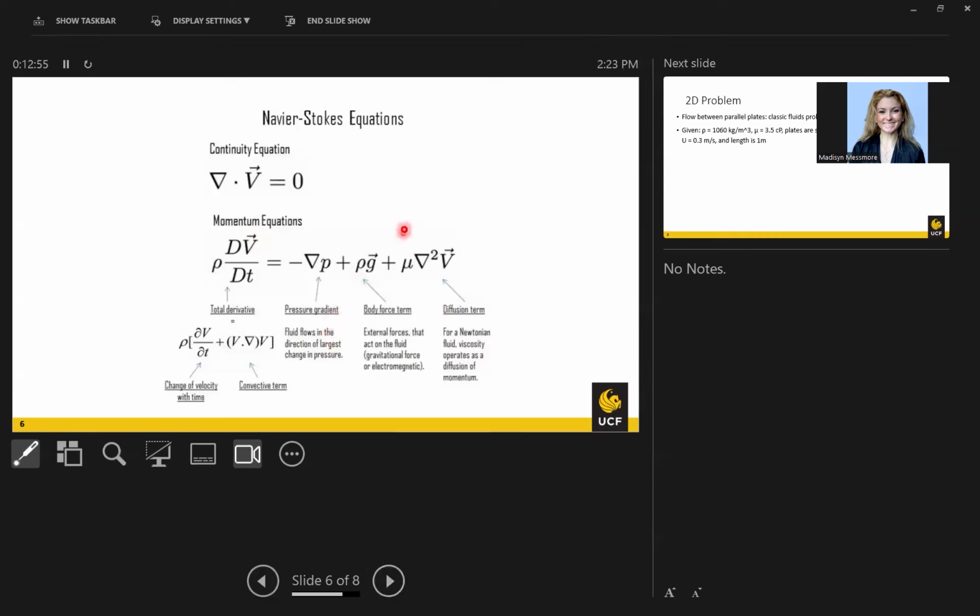Other than just to reiterate what the Navier-Stokes equations are. The continuity equation is your conservation of mass. It's effectively saying that the divergence of your field, so the net flow coming out, is 0. It's just conservation of mass, really, is all that is. And then conservation of momentum. This is an easier way to write all 3 dimensions in one. It can also be rewritten into other coordinate systems, but that's another gross thing to talk about. So yeah, that's all the background.